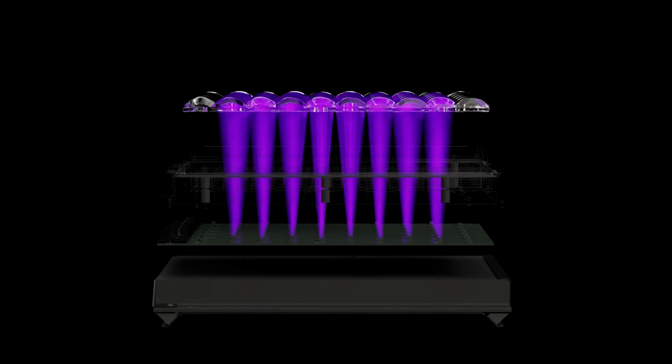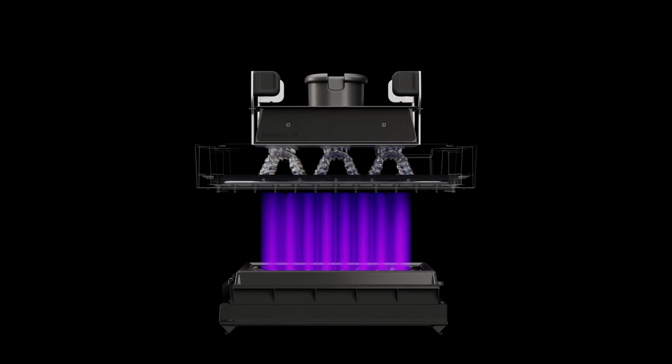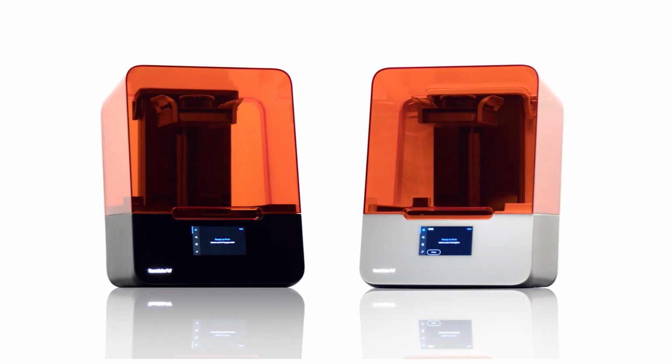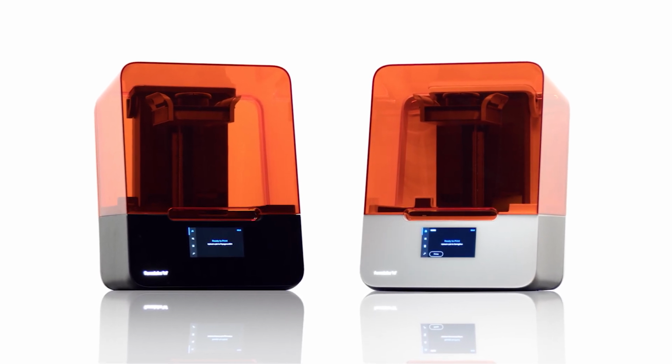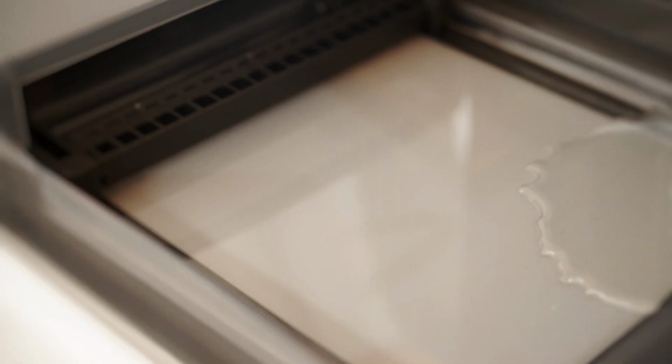Light shines up from the LEDs in the backlight unit, up through the LPU and release texture, and into the resin tank. In Form 3 and Form 3L generation printers, the optical surface most likely to be contaminated is the glass optical window, which sits atop the light processing unit, or LPU. Laser light from the LPU shines up through the optical window and into the resin tank above. Use this guide to identify common print failures related to contaminated optics.